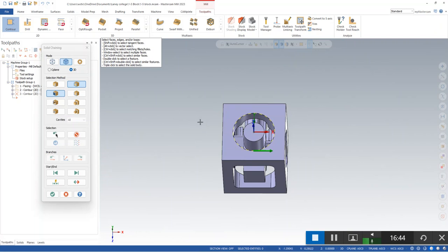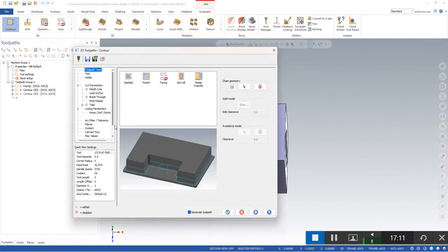the end mill is going to climb mill and conventional mill, so we can go back and clean it up afterwards, but for now we just want to make sure that we're going counterclockwise if you choose the outer circle. That way with our left compensation it's going to compensate to the correct side. So green check.